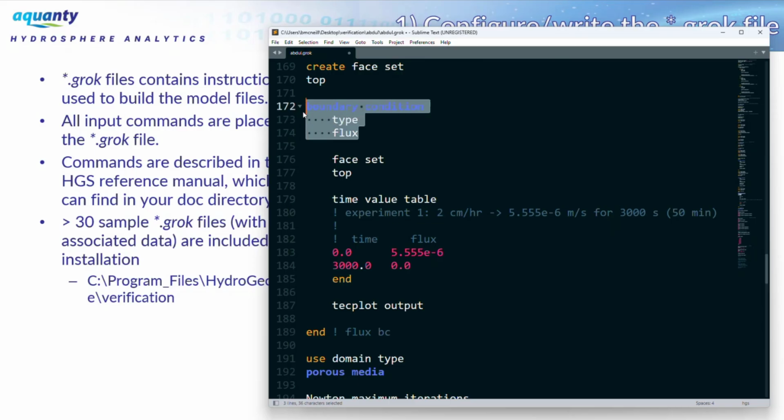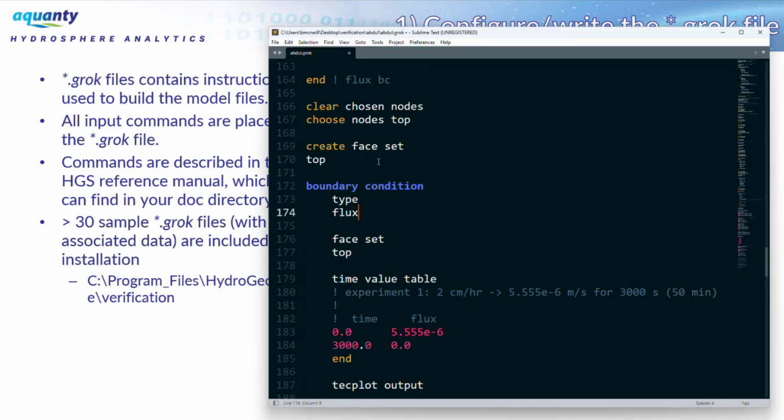As I mentioned earlier with HydroGeoSphere, the real physics-based approach, the principle of physics-based modeling is just rain on the model. Well, this boundary condition here represents rain. It's a specified flux of rain which is being applied sort of homogeneously to the top of the model.